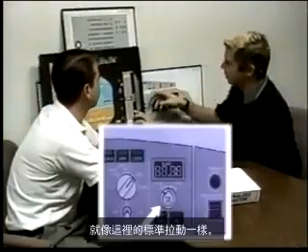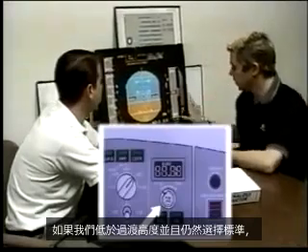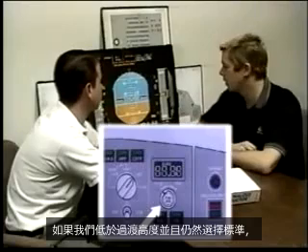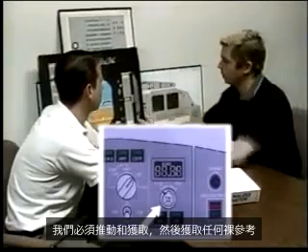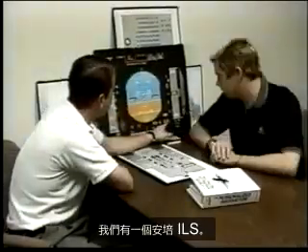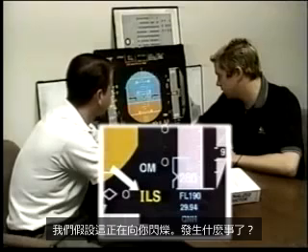We have to pull for standard here. If we are below our transition altitude and we still have standard selected, we'll have to push and then give whatever barometric reference we want to set for it. We have an amber ILS. Let's assume this is flashing at you.